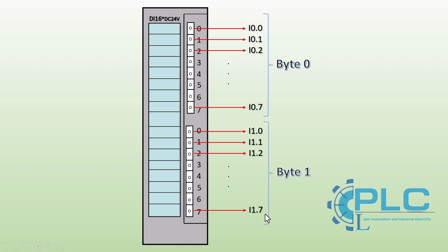In this video, we covered creating a new project in SIMATIC Manager, performing hardware configuration for the PLC, introducing OB1, Organization Block 1, the main execution block in the program. In the next video, I will introduce bit logic instructions and demonstrate how to write a ladder logic program to control a motor. Stay tuned.